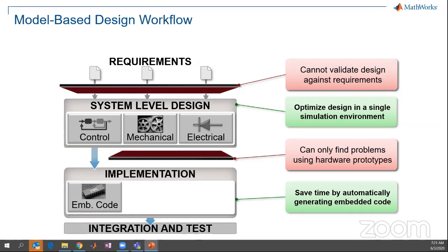The challenge that we often heard from our customers is that before they used model-based design, it was hard for them to manage the project, because the previous C code was designed a few years ago, and due to the inconsistency between the production code and the simulation model, they have to redo the test and verify the design all over again. With model-based design, we can always go back to the simulation model, change it, and generate code. So we can always have the latest up-to-date code and model.